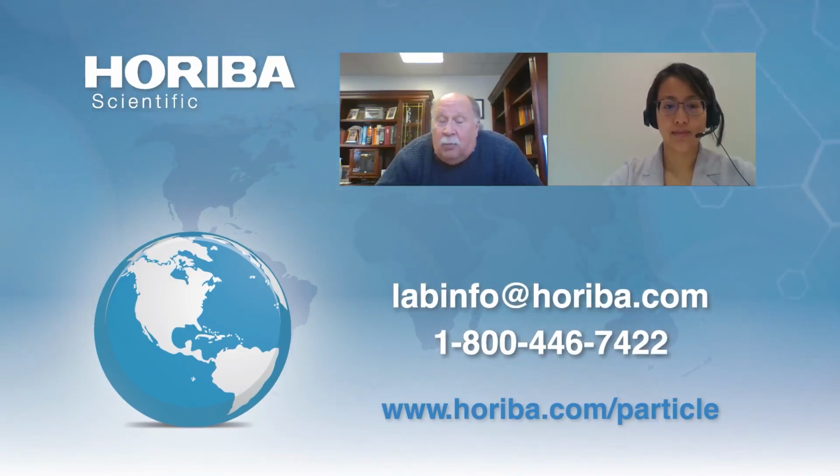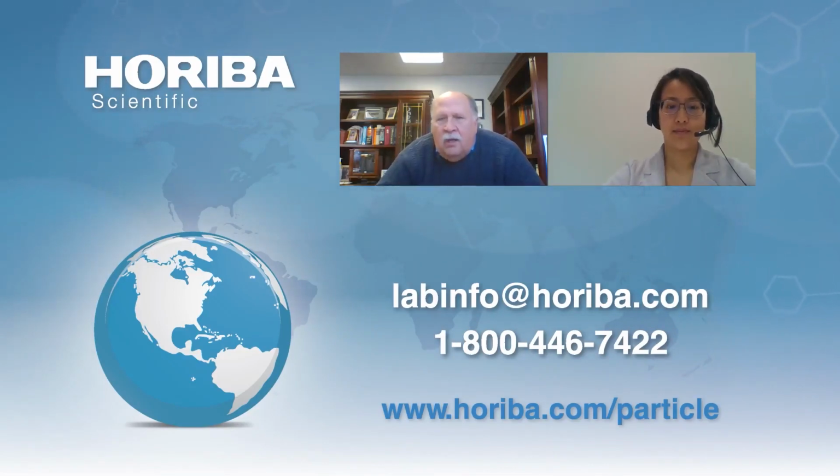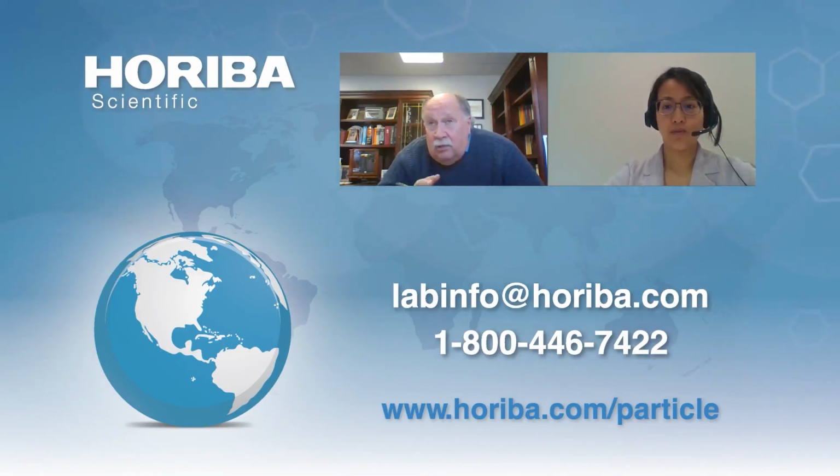Typically when you want to make powders flow better without agglomeration, you put flow aids in. Flow aids are typically small amounts of fumed silica that act as standoff particles that keep things from agglomerating. Not knowing exactly what your application is, I would start with a little bit of fumed silica, and if that doesn't work, maybe we should talk.